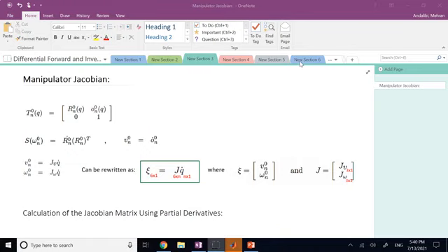Because if you look at the end effector, in general it can have 6 degrees of freedom. Those degrees of freedom come from the rest of the joints of the robot. Those joints can give this end effector its x, y, and z motion, as well as theta x, theta y, and theta z, the absolute angle of the end effector frame with respect to the inertial frame. If we call those absolute angles theta x, theta y, theta z, so not Euler angles, absolute angles.